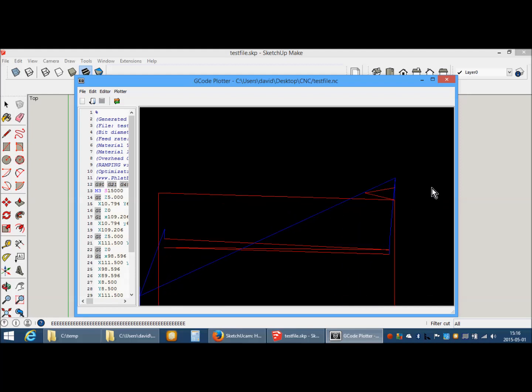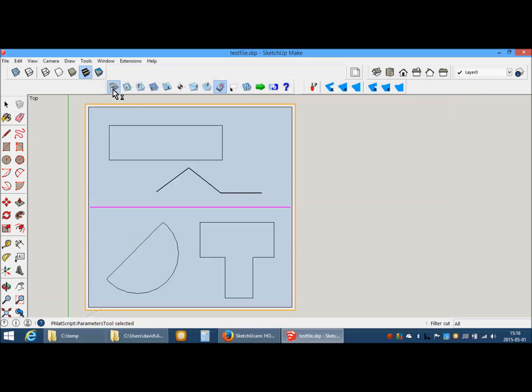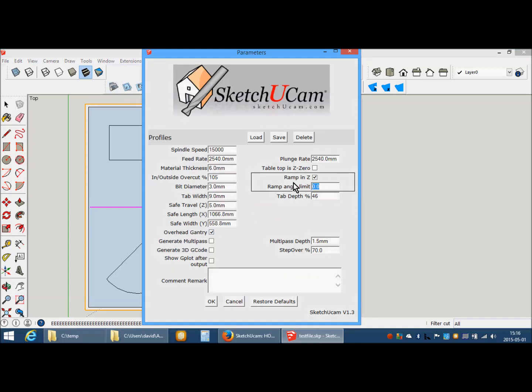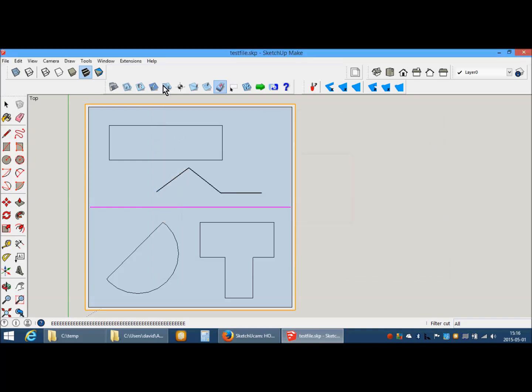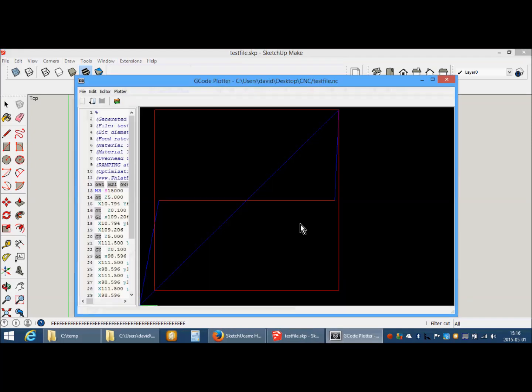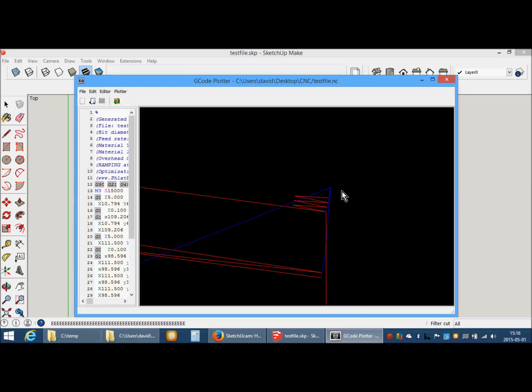and you can see that it now uses a short ramp. Because we have not limited the angle, it is quite steep on a short segment. If we now change the angle, 0 is unlimited, 1 to 45 is a limited angle. Regenerate that G code. And we can see that because of the limited angle, it has now generated multiple passes to achieve the depth of cut.